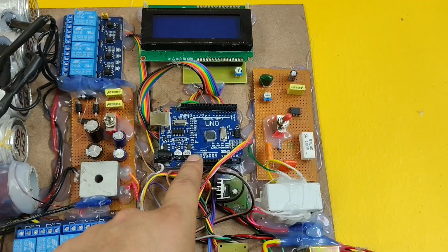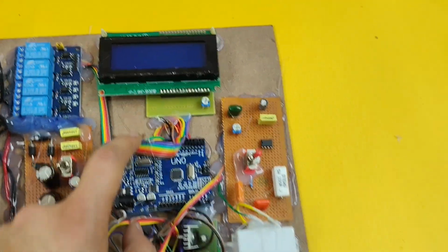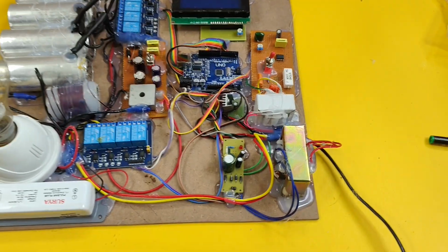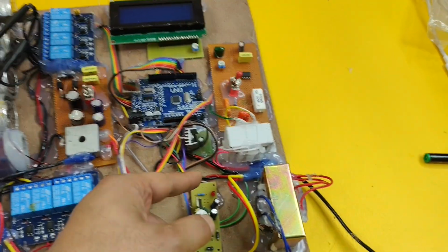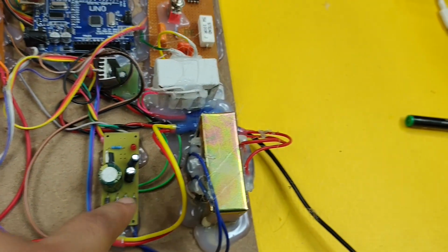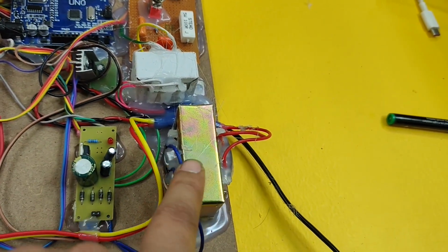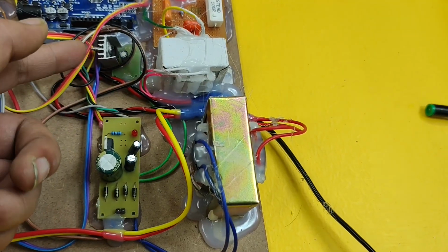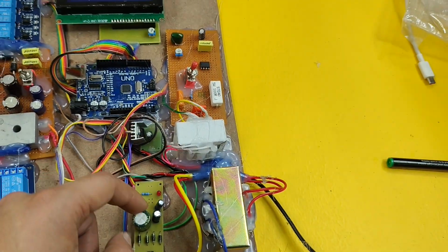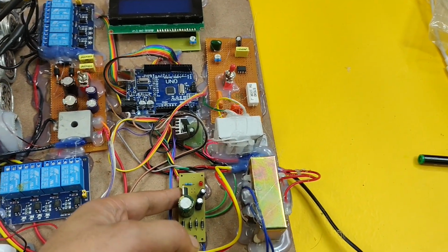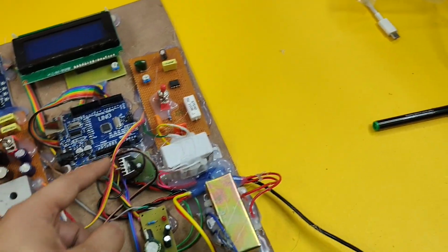And this is the Arduino Uno which is processing all the information. This is the LCD, which is a 20x4 big size LCD, which will display all the information in the project. Again, this power supply, this rectifier circuit, you can see that over here we are using, because we are directly converting 12 volt AC from this transformer into DC. So this is 7805 1 and 2. We are using two 7805 because we need 2 relay boards. One 7805 is heating a lot. That's why we are using 2, 1 and 2.